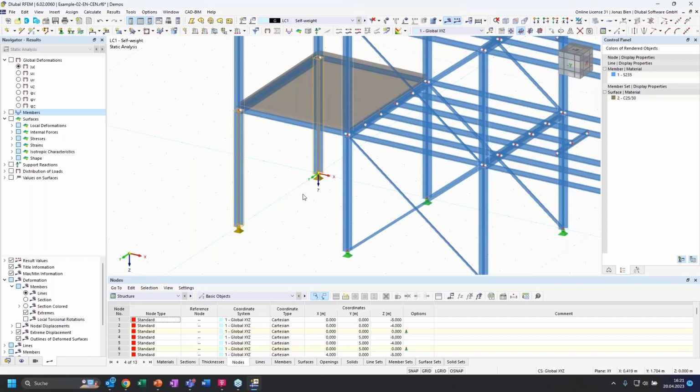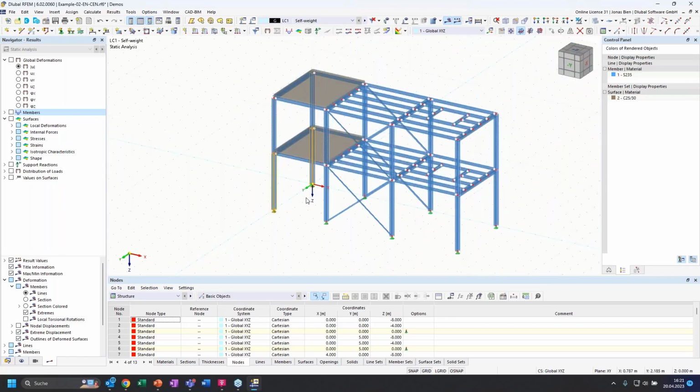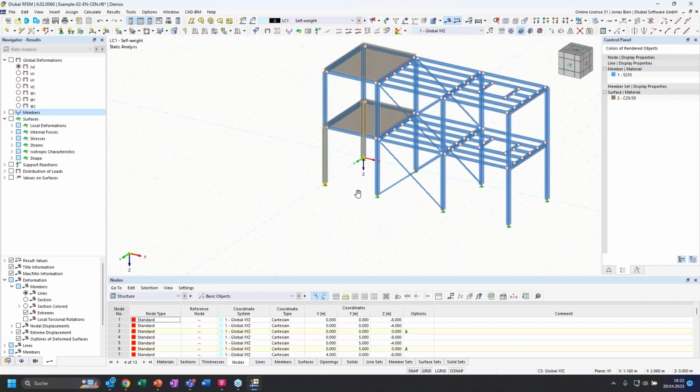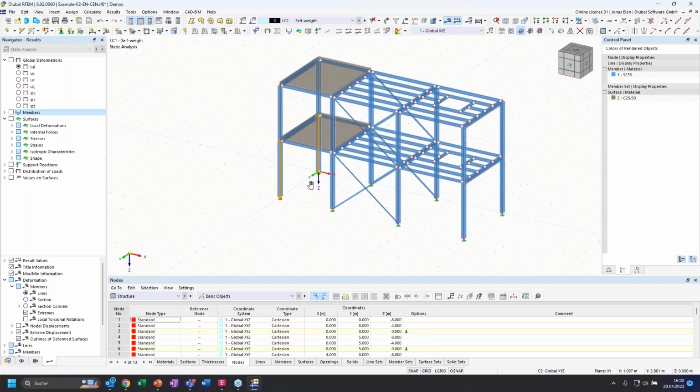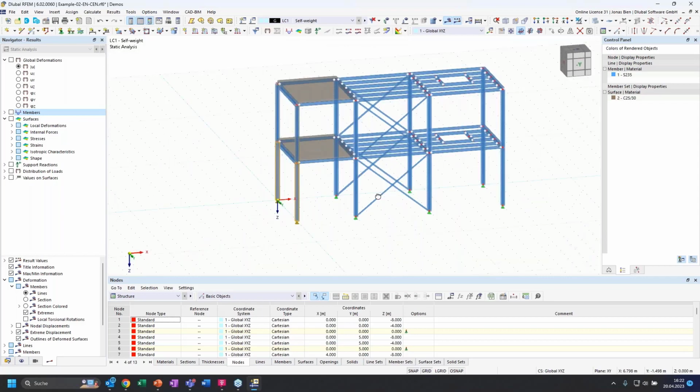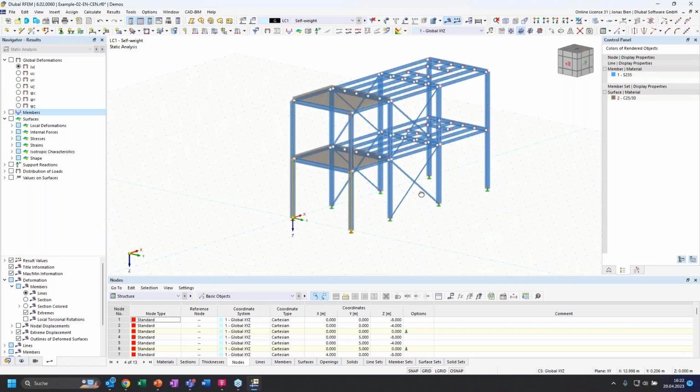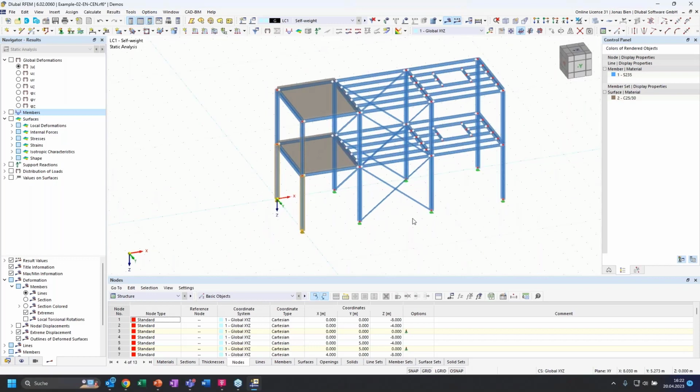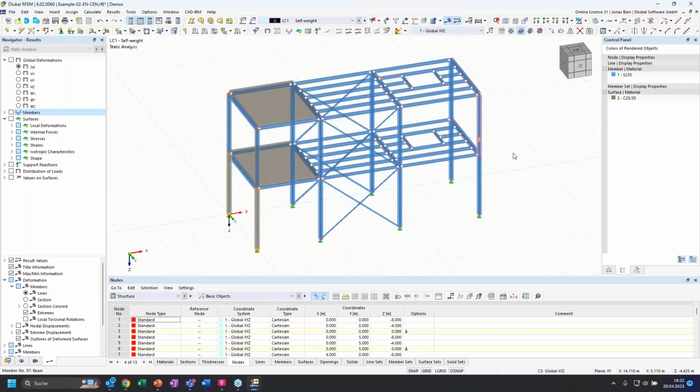Then you have the middle mouse button. You can use it, of course, for zooming very intuitively if you scroll on it. You can press it to pan your model from left to right or up and down. Then you can hold your Control or Alt button on your keyboard and press your middle mouse button to change the viewing angle. And if you double tap on the middle mouse button, it will auto fit your model in the workspace. So the middle mouse button is very important to navigate your view.